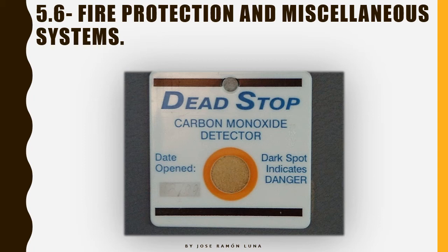Anyway, CO, or carbon monoxide, is a gas that might form inside of the cockpit due to leaks in the engine. Okay, a carburetor engine or an injection engine might form some gases that are going to be coming inside of the engine. This is not happening every day, but if it happens, these gases are usually highly toxic, and this is a threatening situation for us as we are mid-flight and we don't want to get intoxicated, right? We don't want to get sick.